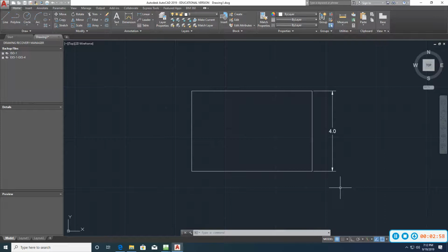And that's an important thing, because if you're going to design something that a machinist has to make, and you've got 3 decimal places versus 1 decimal place, it costs a whole lot more money to make something with 3 decimal places versus 1. The tolerances are much tighter. Okay, sometimes as much as plus or minus 1/1000th of an inch, whereas something that's 1 decimal place might be plus or minus 1/10th of an inch. So you see you have a lot of wiggle room there when you have less decimal places.